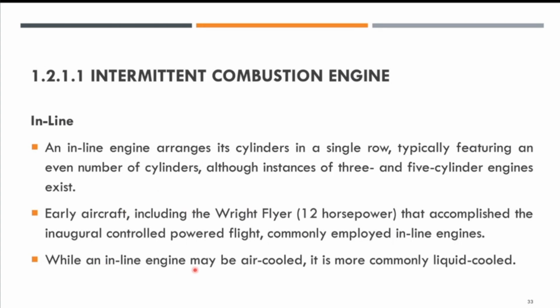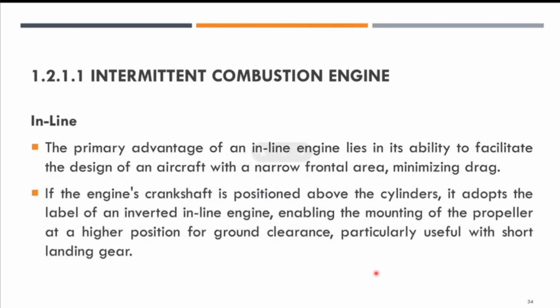While an inline engine may be air cooled, they more commonly use liquid to cool the engine. The primary advantage of an inline engine lies in its ability to facilitate the design of aircraft with a narrow frontal area. If you are designing an aircraft, you want it to be as narrow as possible to reduce drag.